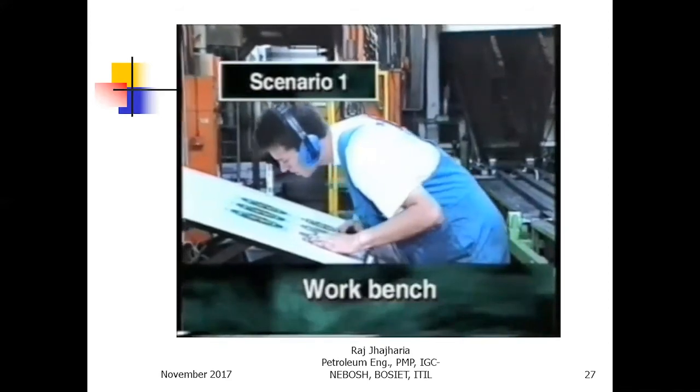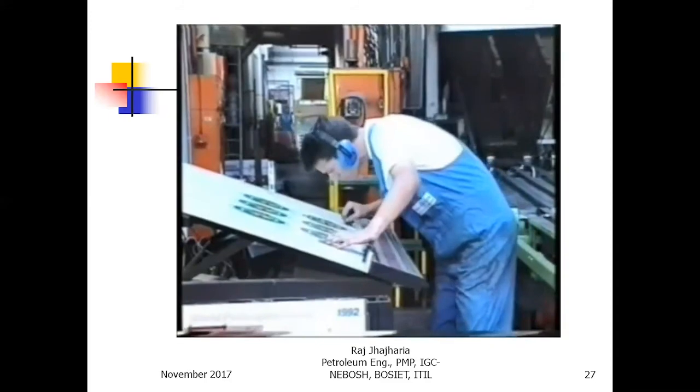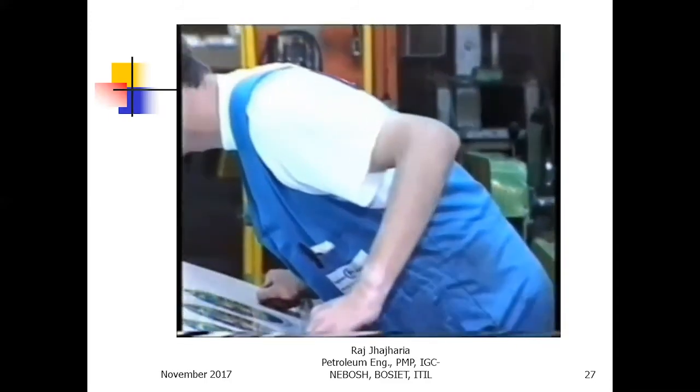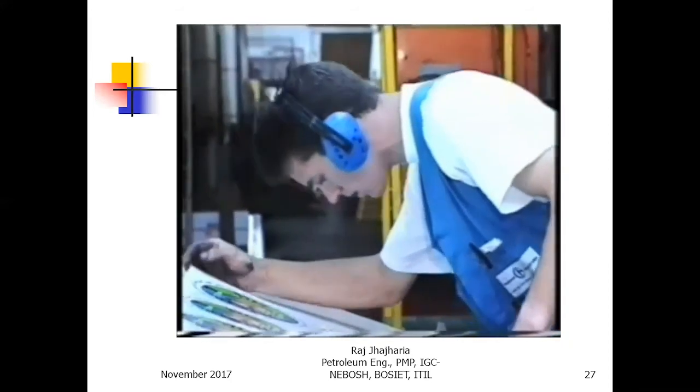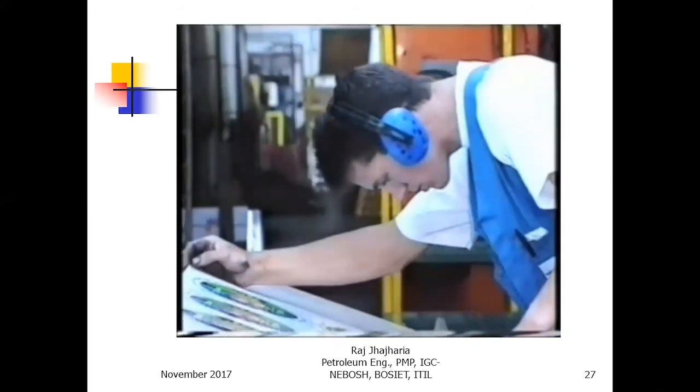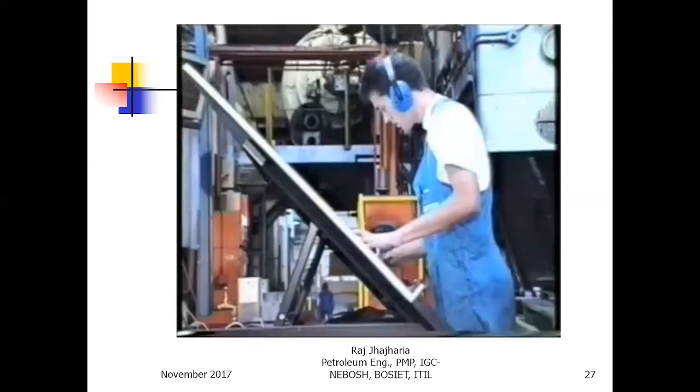In our first example, the workbench is positioned too low for the detailed work being undertaken. As a result, the trunk and neck are bent and the body is hunched. If this position is held for a prolonged period, then pressure will build up on the lower back and neck. To alleviate the problem, the workbench should be raised and angled to suit the employee.